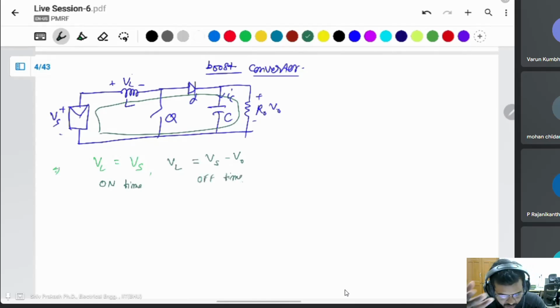All of you know how this works, but why do I ask this? There is an inductor and a capacitor, but this is a DC supply. Then how will it work? In DC, generally an inductor is short circuited and a capacitor is open circuit.